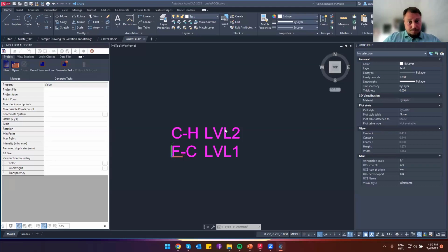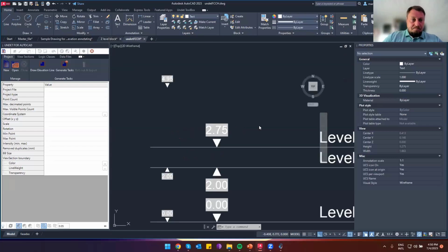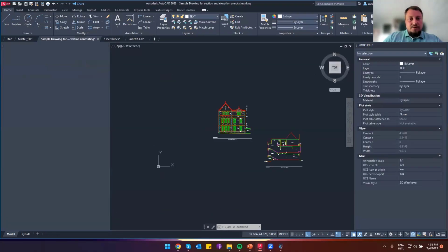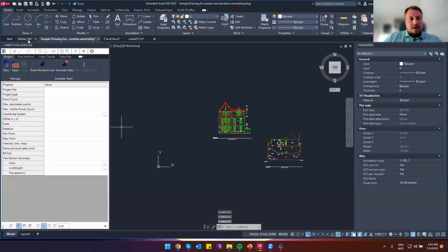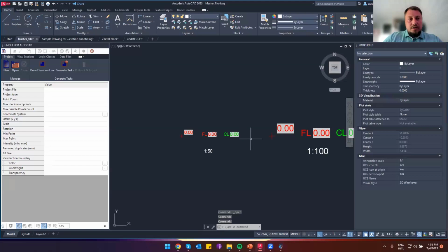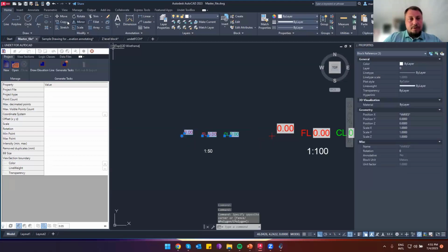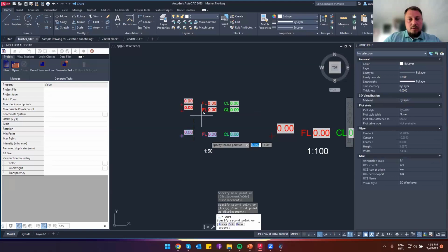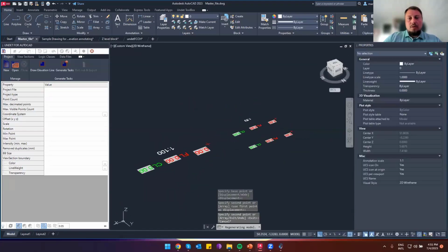Okay, and Need is telling that sometimes my levels break and show a dash symbol. It's possible to fix, but it is not so easy. What we recommend when you're annotating the floor plans is, once you're done annotating, simply use the burst tool to explode this annotation into text blocks.